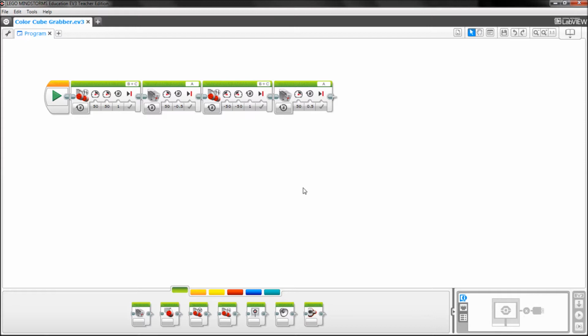Okay. Also, I noticed some of you have robots with different wheel sizes again. For example, one of your robots is using tank treads, one of you has much larger wheels, and one of you is using the standard size wheel for your robot. Just make sure you keep in mind that the distance is going to change. It may be different between your robots. For example, one rotation, instead of being 10 or 12 inches, might be 8 inches.